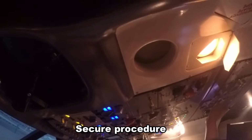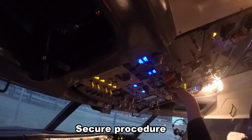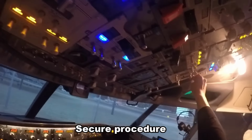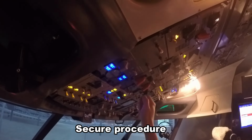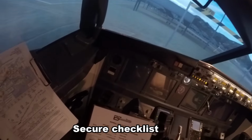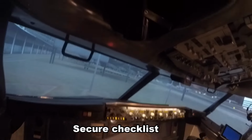IRS is off, yaw damper is off, fuel pumps are all off. We'll turn off the emergency exit signs, window heat, all is going off, packs are going off, and then we'll turn the APU off, and then we'll turn the batteries off. So secure checklist, IRS is off. Emergency exit light is off, window heat is off, packs off. Secure checklist is complete. And that concludes the circuit flight.